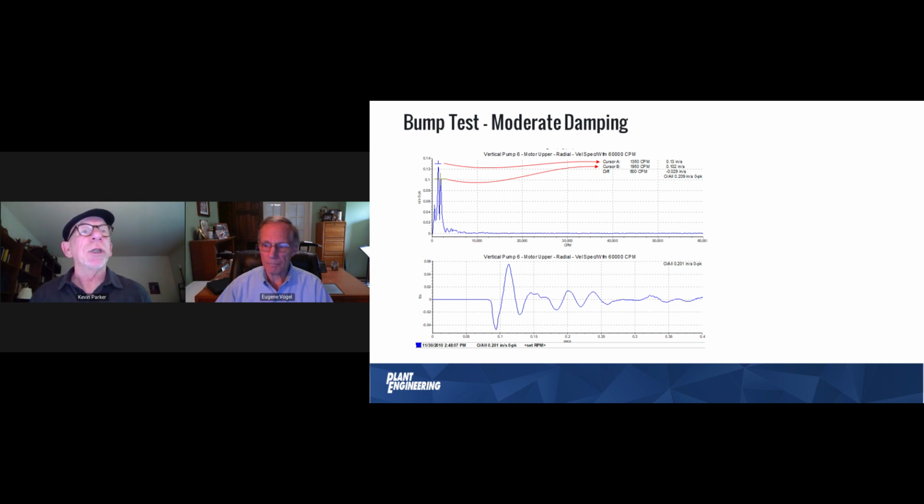When accelerometers are applied to a motor and pump or motor and fan, where are the best places to locate those accelerometers? On the bearing locations, yes, on the bearings. If you've only got one transducer, one accelerometer to put on there, it would be a good idea to take a portable analyzer out there and measure the horizontal and measure the vertical and measure the axial.